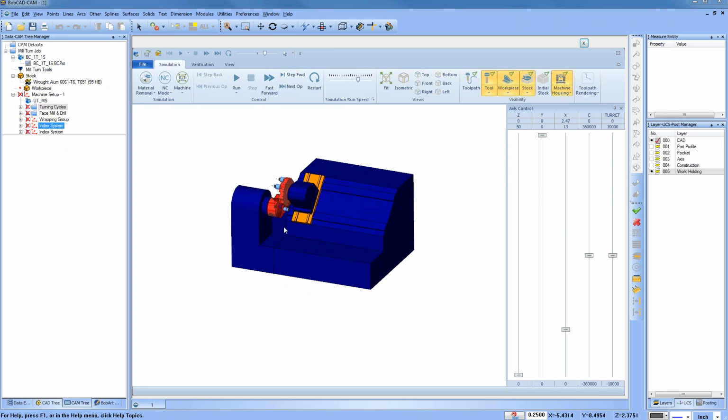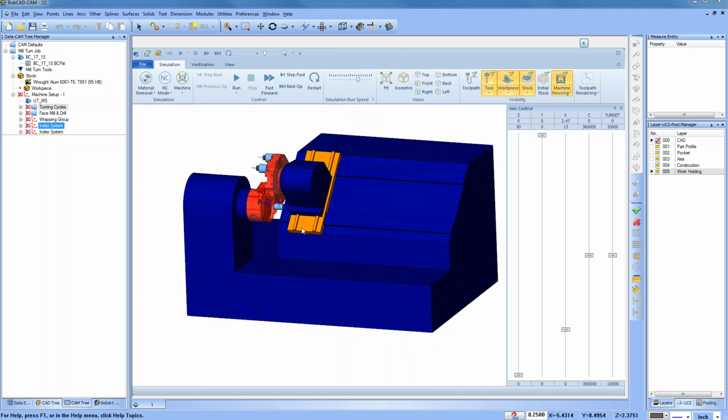There was a question that came in: MillTurn in one folder and mill drill in another folder. Can you get the operations in any order you desire? Mill cycle before turning completed? Yes, Russ. The folder just organizes the features in the tree. As far as the posting order, that's done with the machine posting, or, I can't think of the name of it off the top of my head, but I'll show you here in just a second, where you control the order in which things are posted, either by tool dominant, by feature dominant, etc. So that applies whether it's in a folder or not. Okay, so that's a little bit about the collision checking.